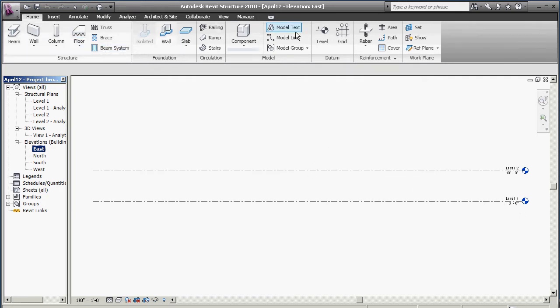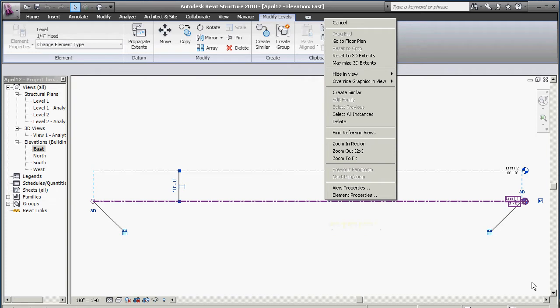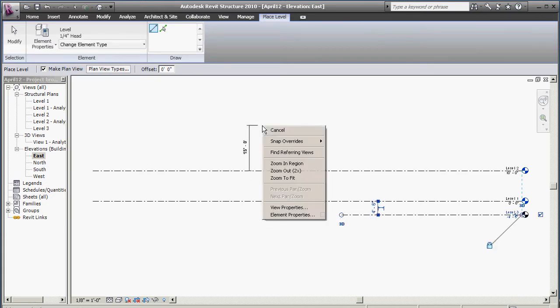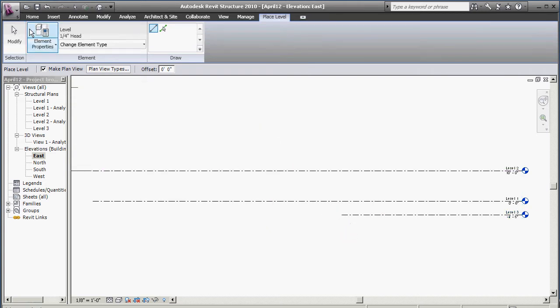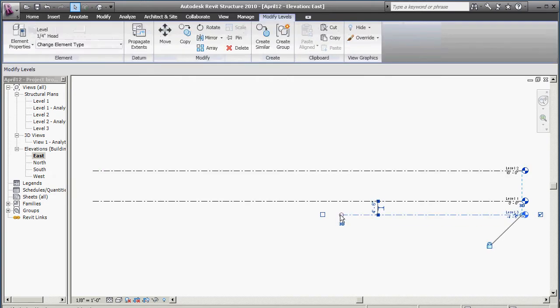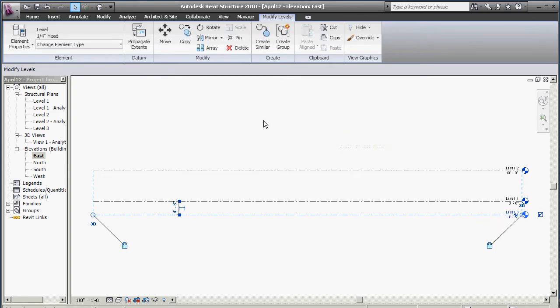So we're going to go ahead and go to level here, and then create a similar. Right, and we're going to go down. We'll just go 4, 6 below there. Click on that, and we pull it across, and right click, cancel. And so now, as you go to here, this was a level, and if you notice, you could have just done it there as well. So you click on that, pull it across, and it may even not be long enough when we get into this later. So we've got a level here right away.